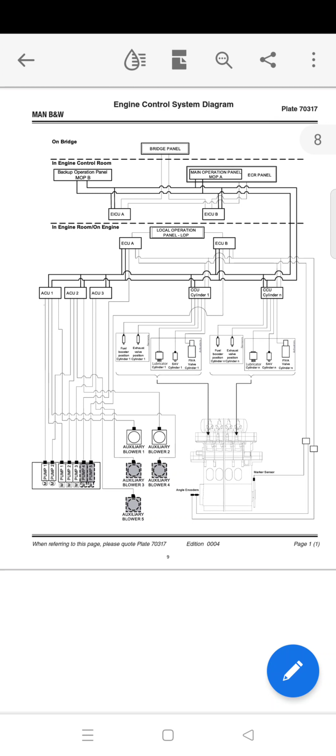So I will tell you one by one, in a step by step manner, so that it will be convenient to understand. So the engine control system, ECS, consists of a set of controllers like EICU. What do you mean by EICU? EICU is the engine interface control unit, which handles the interface to the external system. Now ECU, the engine control unit, performs the engine control functions: the engine speed, running modes and start sequence.